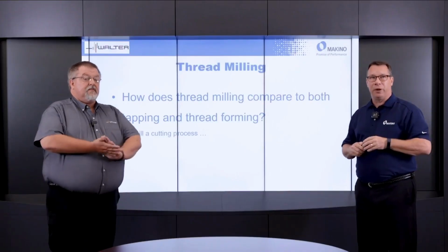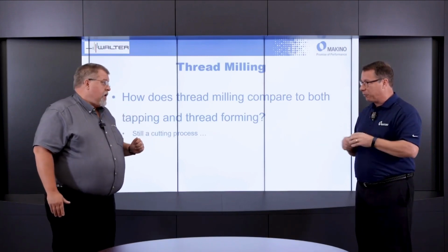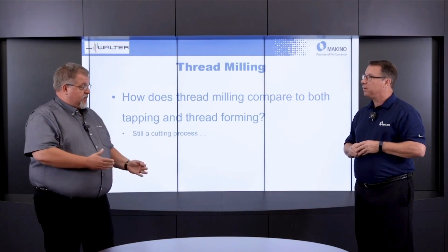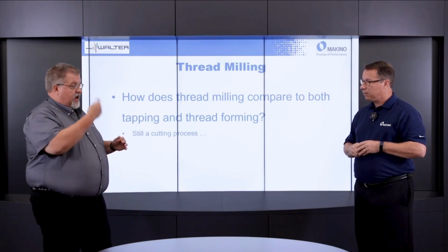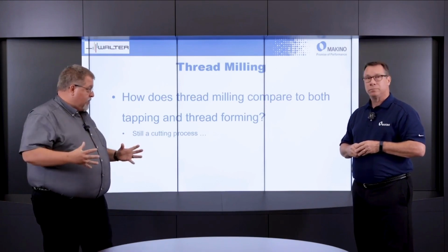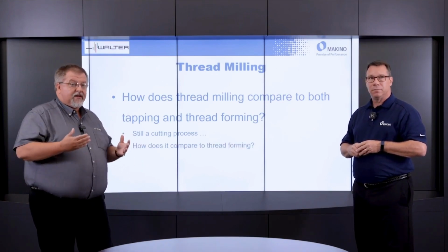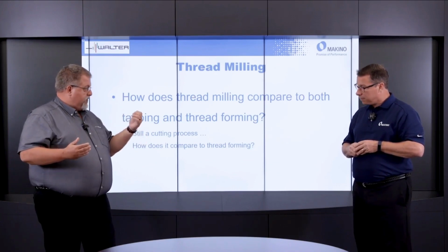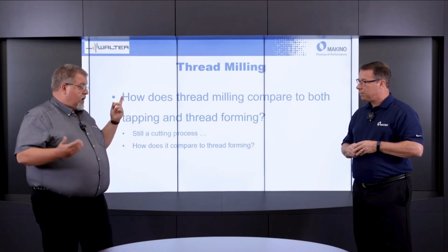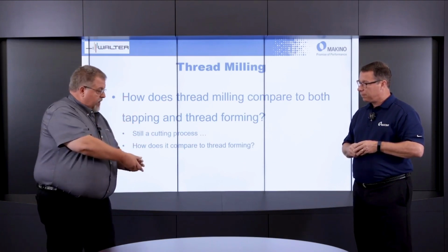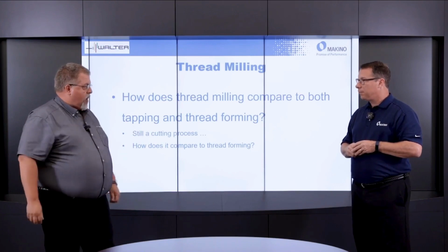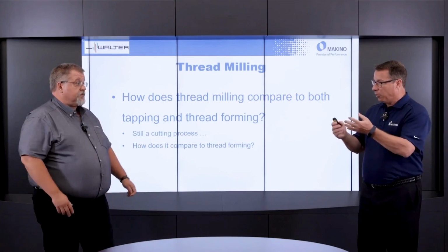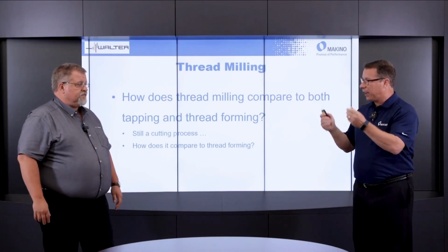So Brian, how does thread milling compare to both the tapping and the thread forming that we've already talked about? It's closer to a tapping situation where we're actually cutting the material. So we are going to be cutting it and removing it from the workpiece. We're not forming it and pushing it around. The method is going to be a little bit different though. We're going to be milling it off the part in real small chips in an orbital sense of milling versus a tap, which would go in and create one single long thread of chips coming off of each flute. So safer from that perspective. It is. A lot less probability of cutting hands, things of that nature.